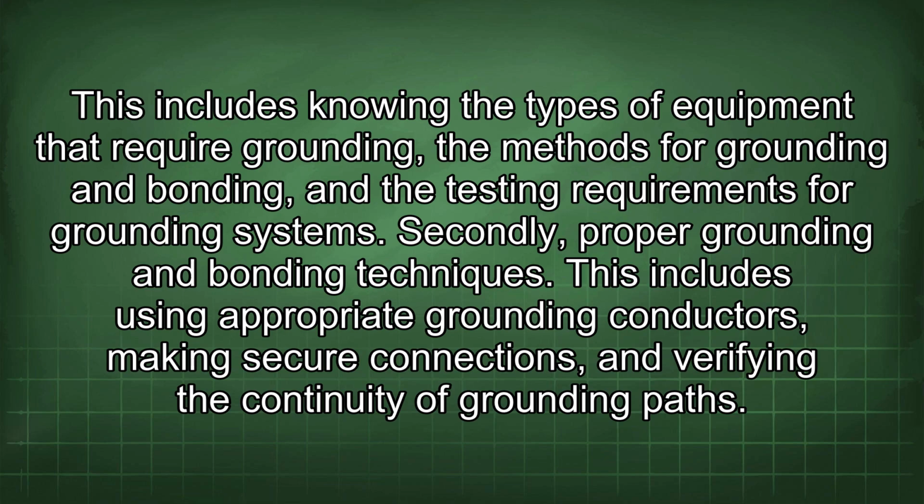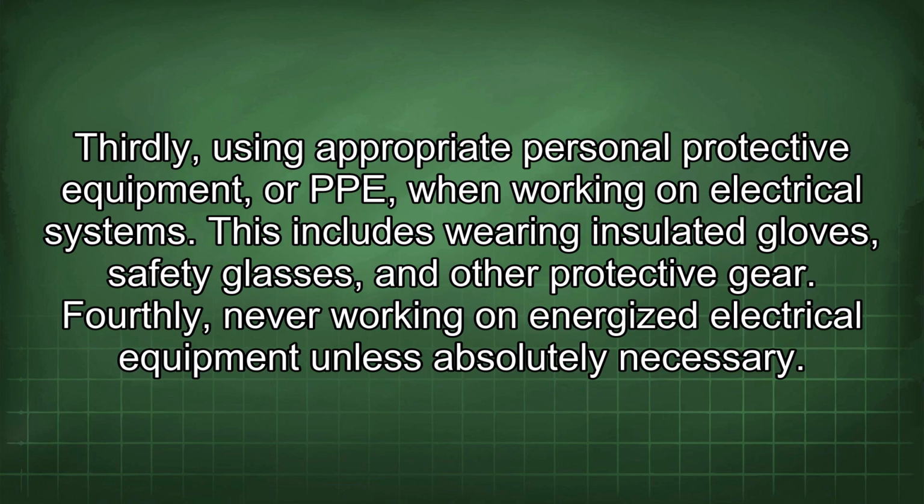Secondly, proper grounding and bonding techniques. This includes using appropriate grounding conductors, making secure connections, and verifying the continuity of grounding paths. Thirdly, using appropriate personal protective equipment, or PPE, when working on electrical systems. This includes wearing insulated gloves, safety glasses, and other protective gear.